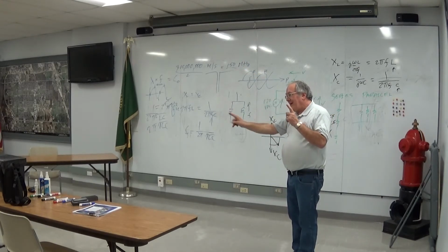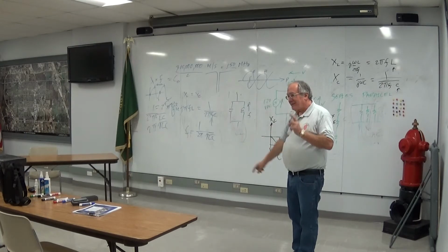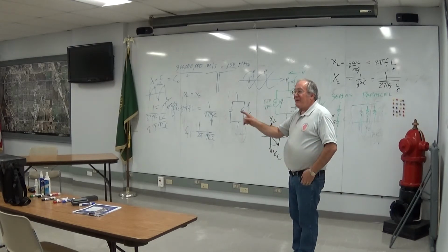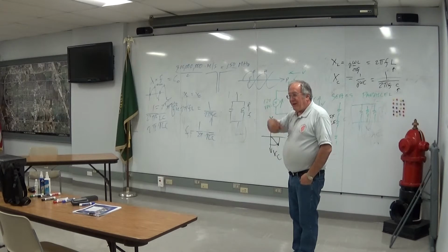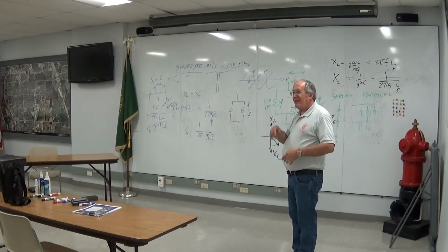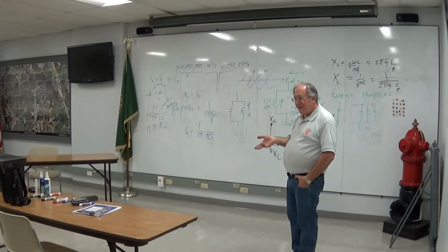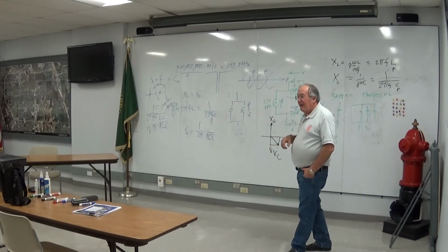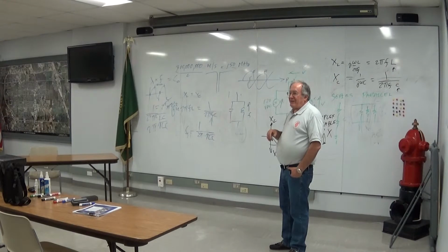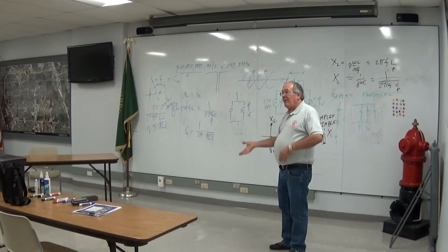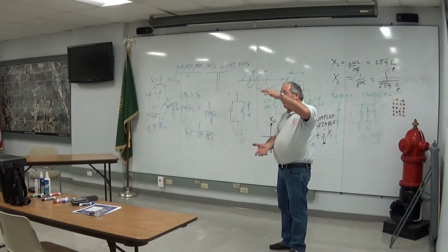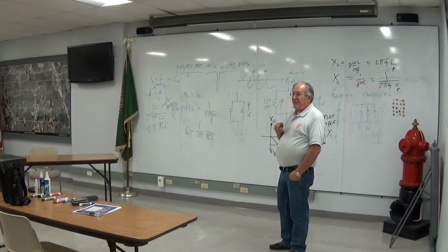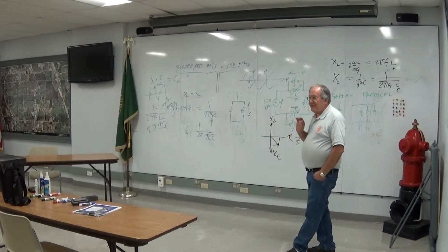Well, the lines are sweeping across the TV screen. There's 525 lines, and there are 30 full frames every second. 30 times 525 is 15,750. That's how many lines were swept on an old-fashioned analog television set. And if you divide 15,750 into one, every single one of those lines took 62.5 microseconds to sweep.